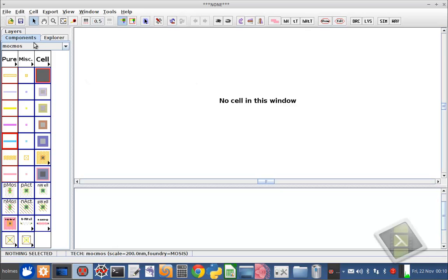So the technology menu library you can see here on the left. This is the MOS technology, and it's organized to enable easy drafting of layouts. You can see here that this is a 5-metal process. There are different metals for interconnect, different metal pins, and then there are metal-to-metal via macros, which allow you to connect, for example, metal 1 to metal 2.